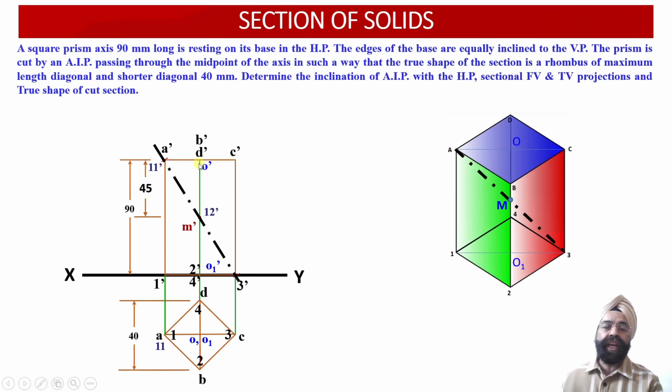Now let us locate this point in the top view projection. So once we look at the edge B2 over here, point 12 will be lying at the midpoint. So we'll find that points B, 12 and 2, all 3 of these points, are going to coincide with each other. Now the third point available over here with us corresponds to the vertical edge C dash 3 dash. This is the vertical edge C dash 3 dash.